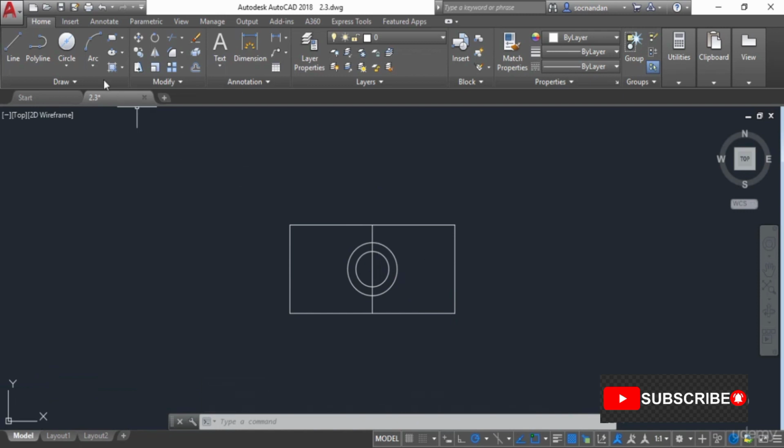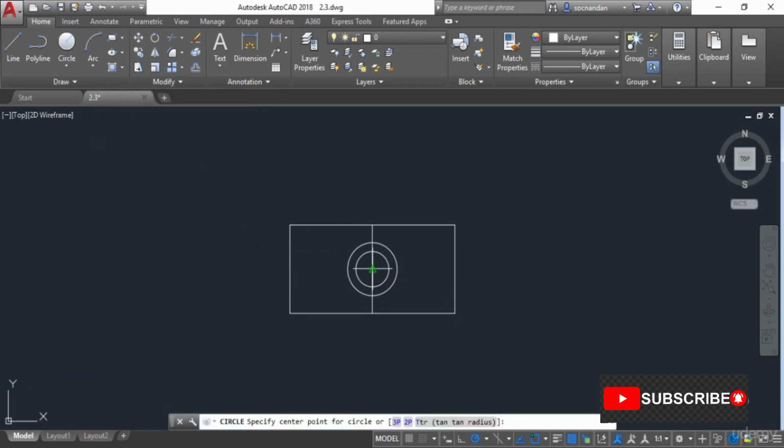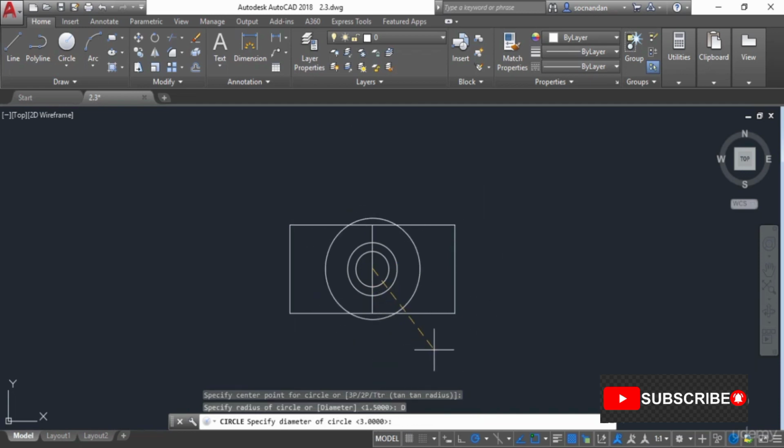You can also start the diameter option from this center radius command. So click on the center radius. Now click at this point or any other point to start the circle, and now you can click on this diameter option on the command line to start the diameter, and now simply enter the diameter value.